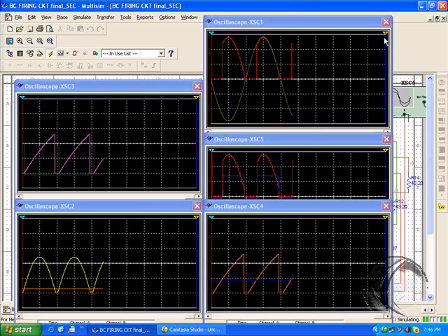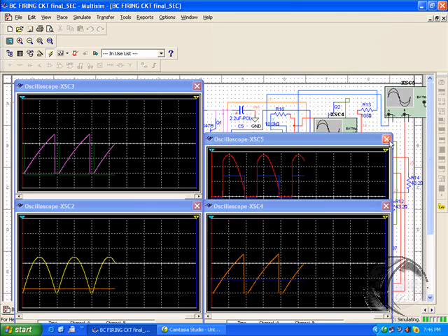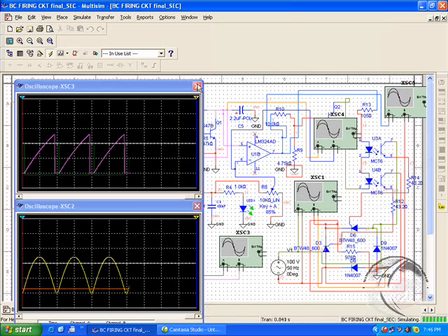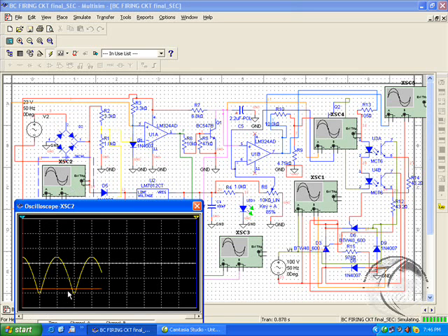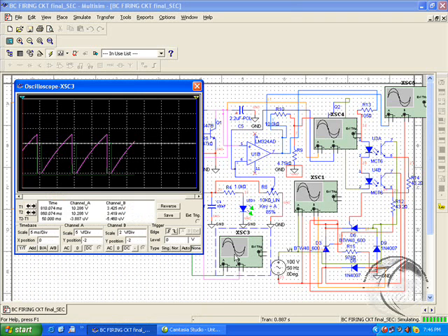Right? Now if we go over to the circuit, we can see all of them in the circuit. Let me remove these CROs. We have the comparator here, and this comparator is with a fixed voltage, and the pulsating voltage is coming from a bridge rectifier here. So what I get here is zero cross detection. This is compared against 0.6 volts, and in the process I get zero cross detection. So these are zero cross detections, right?